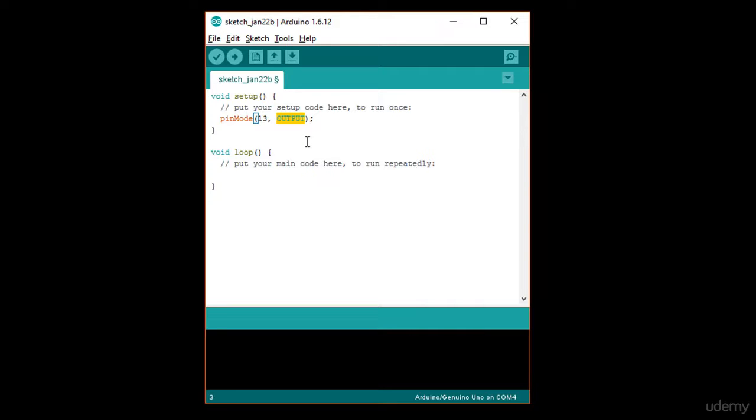If you changed any of the letters to lowercase, you would not be able to compile your program. The semicolon at the end of the line is very important. In C and C++, it marks the end of a statement. Without it, the compiler will likely fail when it tries to compile, and you'll get an error at the bottom part of your Arduino program. We can leave the line with the double slash. It is a comment and will be ignored by the compiler.